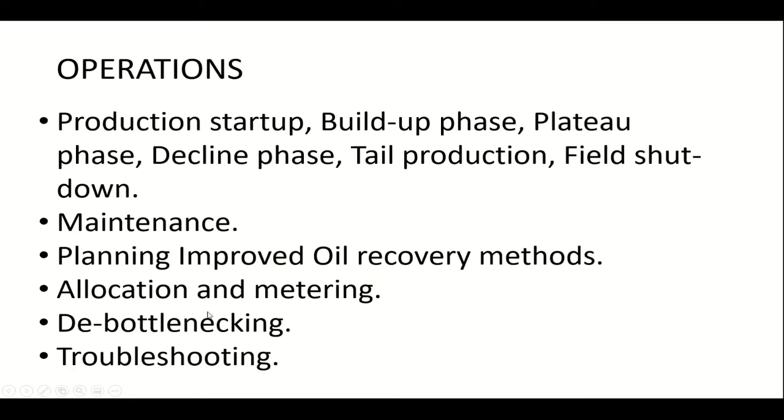Allocation and metering, how much you are producing, because at the end you are splitting. First, you have to report these numbers to the government to pay the tax, but also you have to split sometimes between partners. So allocation is also very important for reservoir engineers, for example, they like to forecast future production. So if they get more information from measurements, then they can have a better model that supposedly will be closer to the actual field.